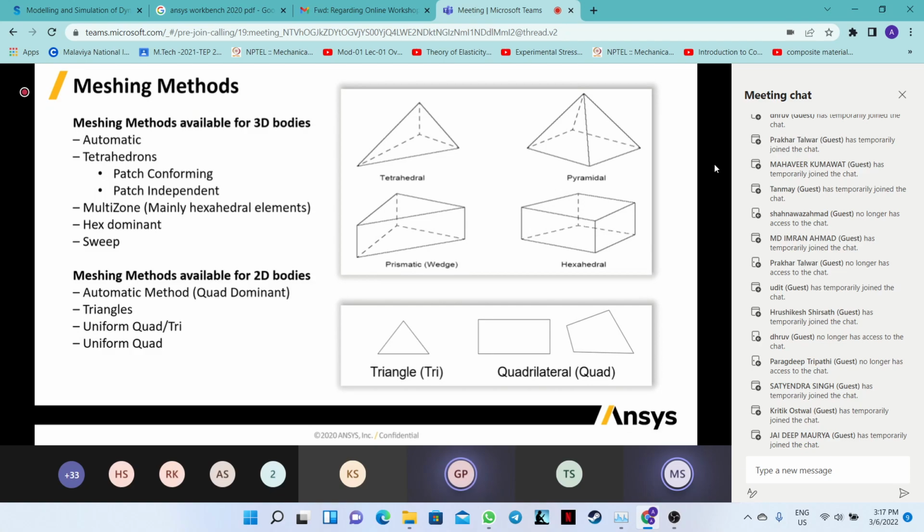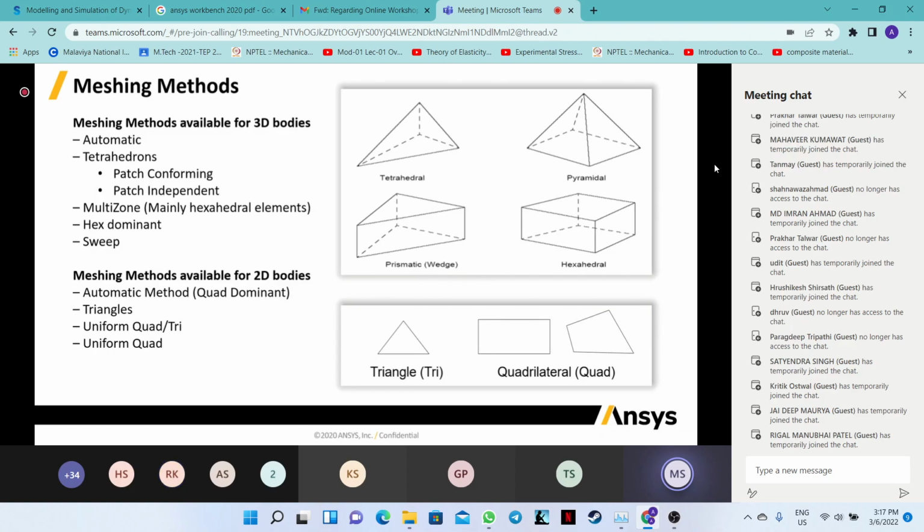The difference comes when you have a uniform cross section throughout your geometry, or a very small cross section change. There it will give you the sweep. You can simply ask the software to show which bodies can be worked with the sweep method. When you generate a mesh with a sweep, you get good quality. It's best practice that whenever you import an assembly, first check for the sweepable geometries, so that half of your tension is gone, as you don't have to work on those components.